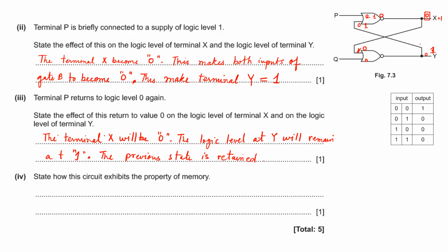So we can say that the outputs X and Y, connected to corresponding inputs P and Q respectively, show which of the inputs last had 1. That is the concept of memory over here.